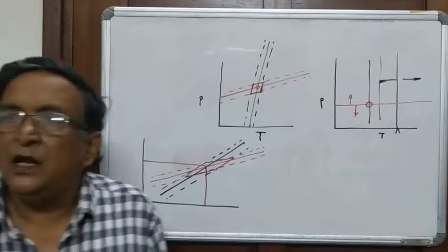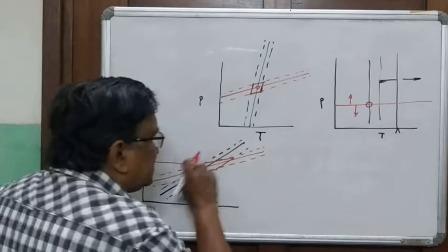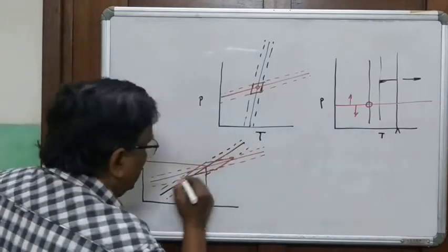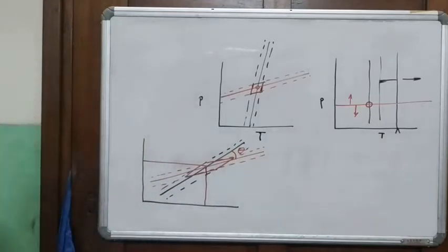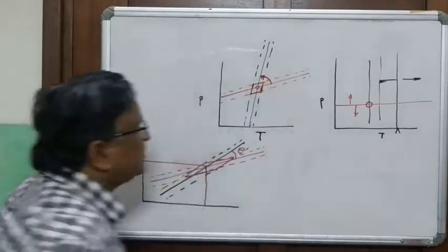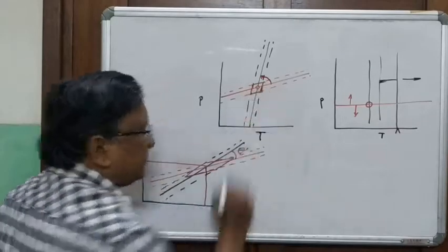So what one normally does is, why is this large error coming up? Because of the low angle of obliquity, which is theta, the low angle of obliquity between the two lines. Here, the angle is much more. Yes? This gives you a smaller error.